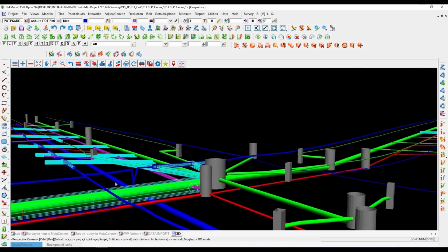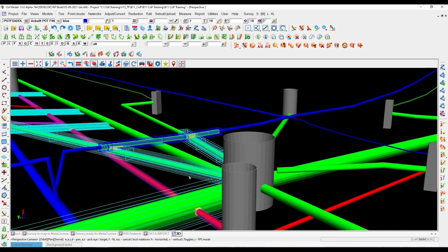So hopefully you wouldn't be having that, but I know a few projects where they're doing asset by asset, so they're doing the stormwater first or the sewer first, and they're designing the other assets based on what they pick up through the installation. So you can take the as-built attribute information and pass that to the designer so they make sure that there's no future clashes.